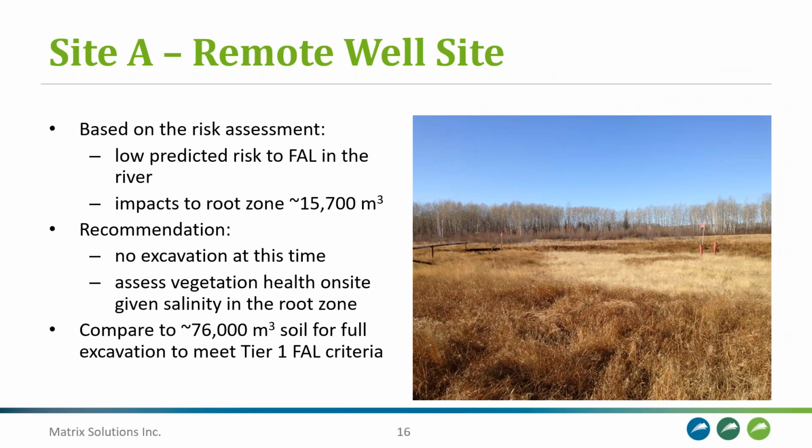So based on the risk assessment, we have a low predicted risk to freshwater aquatic life in the river, but we do have these remaining impacts to the root zone. Due to the sensitive nature of this site, again, it's located within a peatland and also the caribou habitat zone, we're recommending doing a vegetation health assessment to assess the risk to the vegetation rather than going ahead with any root zone excavation, just to determine the health of that community.